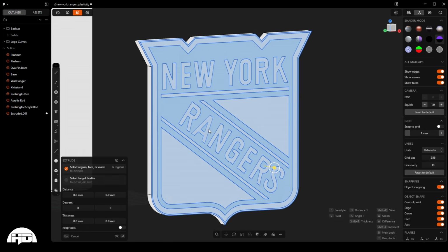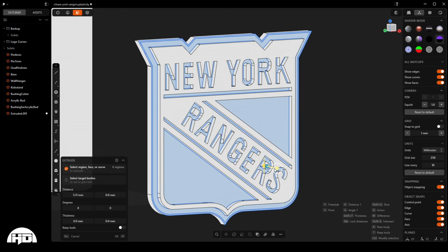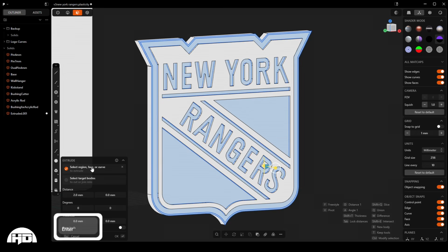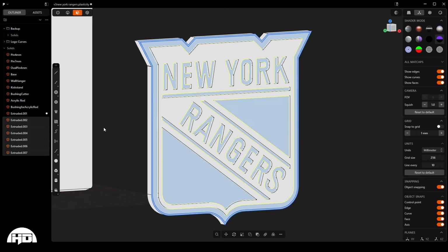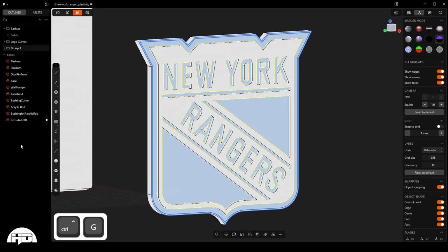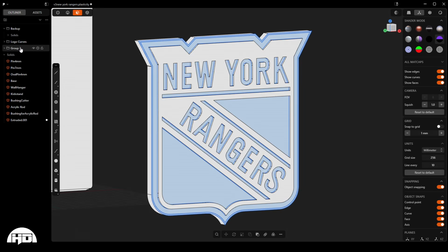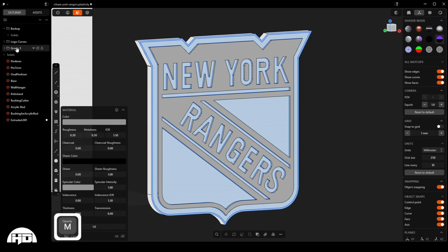So there we go. We've got everything selected. And we're just going to pull on that way. I generally do 2 millimeters, so we'll go right there. Right click to commit. Now, once you commit, all of these are still highlighted, so I will just go ahead and hit Control G to group them. And then we're going to select this group, hit M for material.